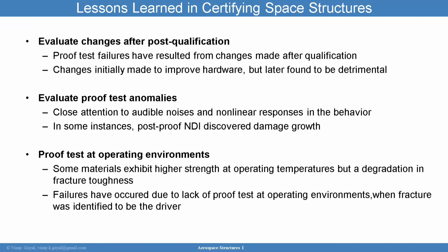So if you can do it, do it. Because if you don't do it, and any of these anomalies in the proof test occurred and it had to do with damage, it can subsequently lead to a flight issue. So again, any proof test anomalies should be evaluated carefully. I'm not saying always implement NDI, but for the most part, you want to make sure you have a good understanding of what went on.